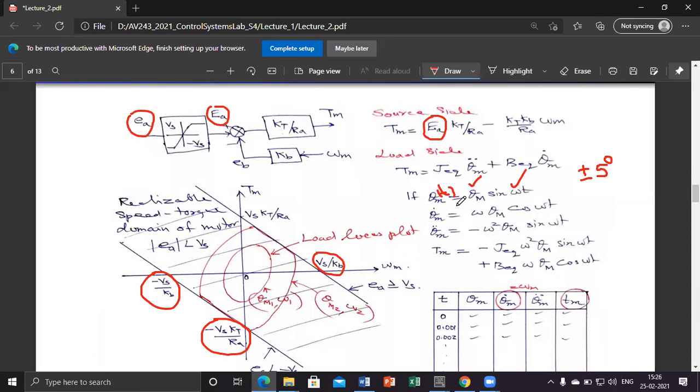If that is the trajectory theta m(t), you can differentiate to get theta m dot and double differentiate to get theta m double dot. And these are the formulas. Then you can calculate the required Tm, the torque required at the driving end. That is how much torque should be generated by the motor to steer the equivalent load dynamics, including internal and load, through a sinusoidal profile like this with a maximum amplitude, that is the amplitude of capital Theta, and a frequency of omega.